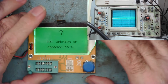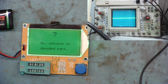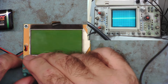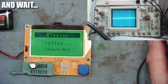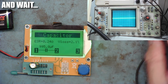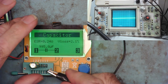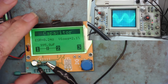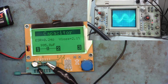So let's have a chat about these things now. This is an alleged ESR meter amongst other things. Yeah, it's a little component analyzer. And if we take a capacitor and put the capacitor on it, then we switch it on, it reads the capacitance and gives us an ESR. Okay, let's connect our oscilloscope probe to it.